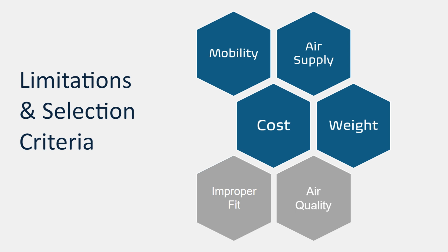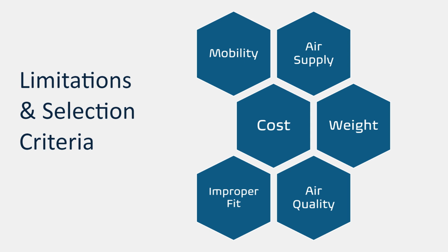Cost. ASRs are more expensive to manufacture and assemble due to the complex equipment required, such as air compressors or breathing tanks. Air quality dependency. The safety of the user depends on the quality and availability of the air supply from the compressor or tank. And improper fit. For tight-fitting ASRs, factors like facial hair can interfere with the seal, and proper fit testing and regular checks are critical for proper protection.